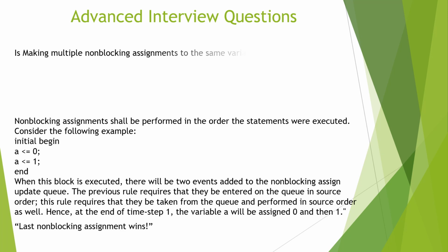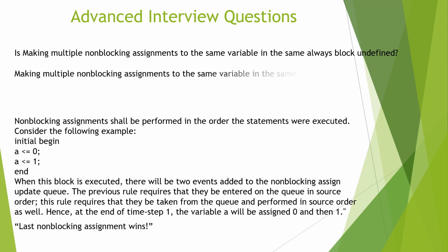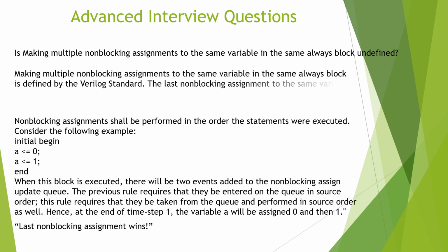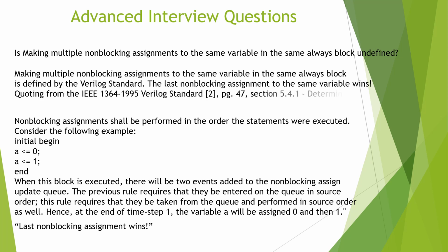The next question is, is making multiple non-blocking assignments to the same variable in the same always block undefined? Making multiple non-blocking assignments to the same variable in the same always block is defined by the Verilog standard. The last non-blocking assignment to the same variable wins. I am quoting from the IEEE 1364 standard.